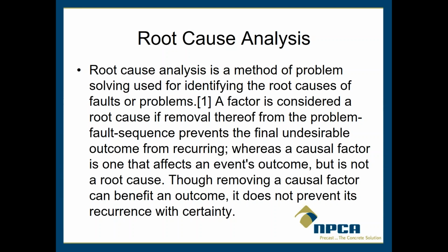the root cause. So for instance, if I have air fluctuations, and everyone's dealt with air fluctuations, adjusting the air entraining dosage is causal. So that gets me where I need to be right now, but that doesn't address the cause of the variation in my air.